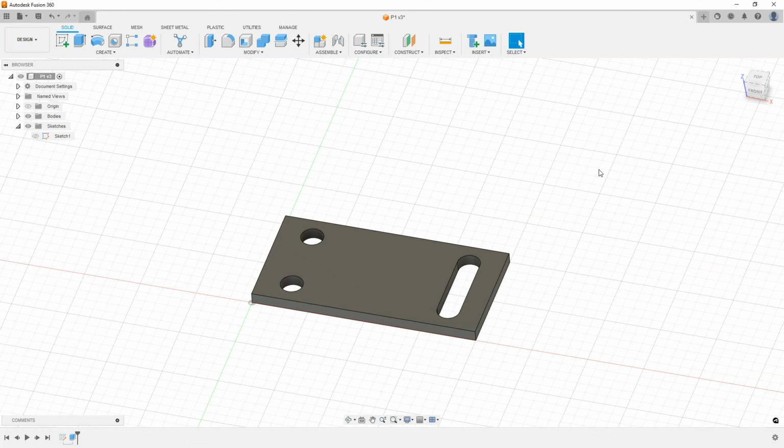And this solid was created from a 2D sketch, and Fusion 360 is a parametric system, and this gives a huge advantage in designing 3D parts. When creating 3D models, we work with parameters, and it may not be visible at first glance, but the dimensions of the sketch or the extrusion distance are parameters that we can edit during design, even if a 3D solid has already been created based on the sketch. This is very useful, especially in projects whose final shape may change.